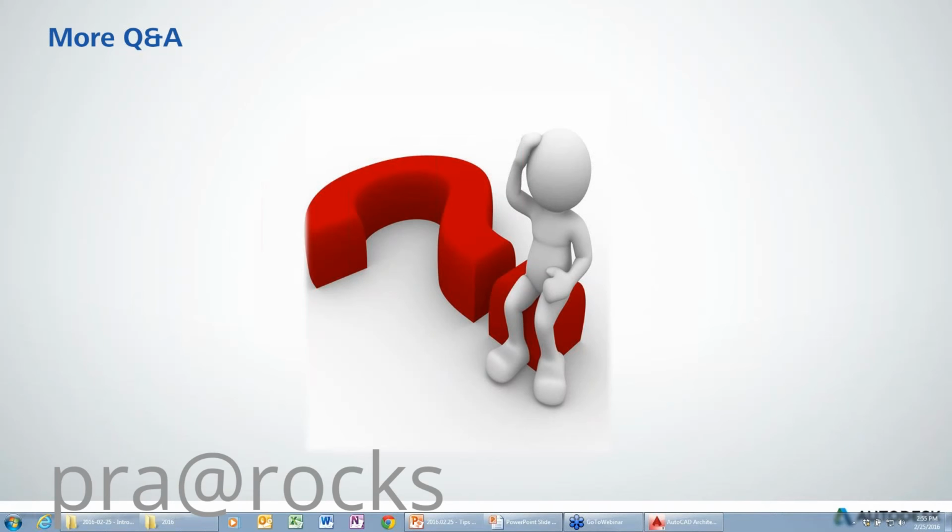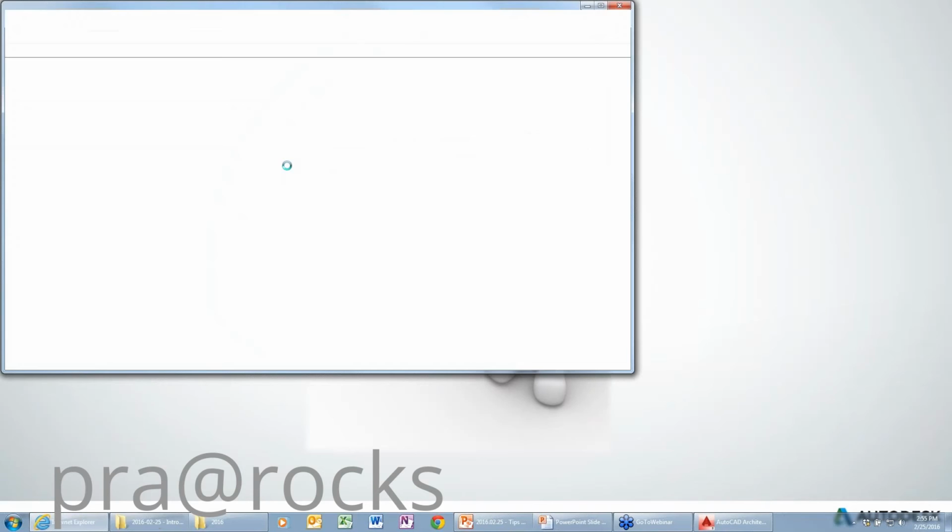Dave, do you have any recommendations for people who don't necessarily have AutoCAD Architecture, but are receiving files from people who are using it, with those AEC objects in them? How do you work with them in regular AutoCAD or LT? That's a great question. The answer depends on what version of AutoCAD you have. The newer AutoCADs, like 2016, have the object enabler for AutoCAD Architecture built right in, so you don't have to do anything. But if you are using an older version of AutoCAD, you may want to just pull up